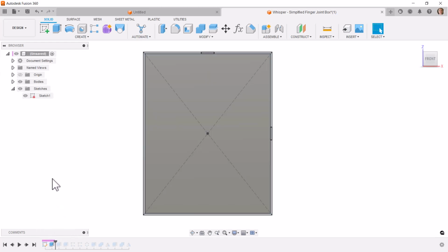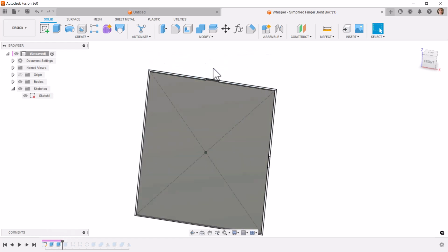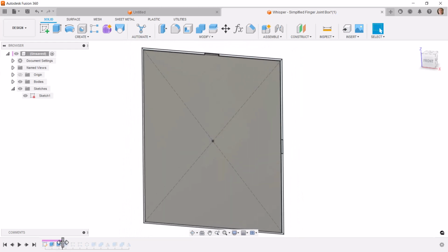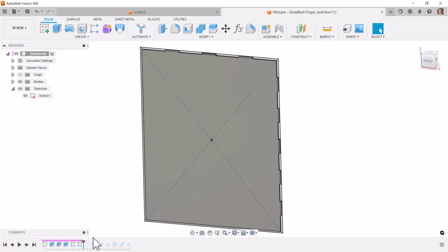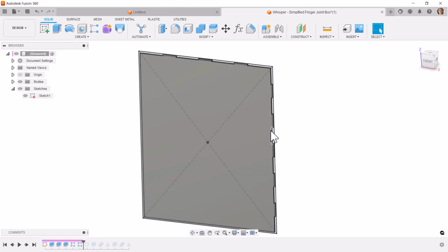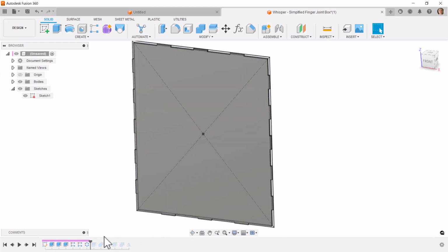And then we extruded the back plate, and then we extruded a finger tab on one side and a finger tab on another side. We did a pattern along the top, a pattern along the sides, and then initially we did 2 mirrors, mirror this over to here, this down to here, but actually we could do that with one circular pattern to get those finger tabs.